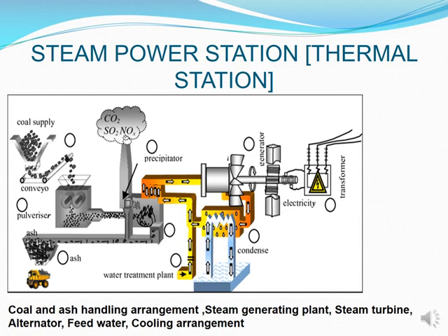Then also, if you're looking at the water side now, after your water has gone into the turbine, the steam would cool off. Remember, it was steam going to the turbine. It would cool off. Then once it cools off, it goes back down. So we recycle the water. It goes back down and condenses, and we call that our condenser. So once it gets to that condenser, it will then be processed into the water treatment plant again. So we send it back to the water treatment plant so that it can be cleaned and reprocessed, and it will go back into feeding again your boiler over there.